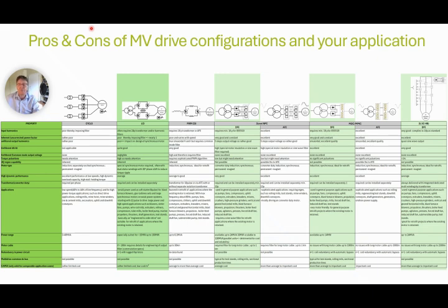Another critical aspect of the output of these drives is the voltage rise, dU/dt. The 3-level NPC neutral point clamped inverter exhibits high dU/dt values. Therefore, the connected motor must be rated for inverter duty to ensure reliable operation and installation integrity.